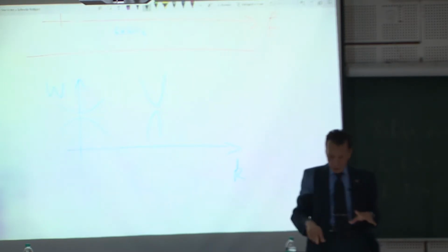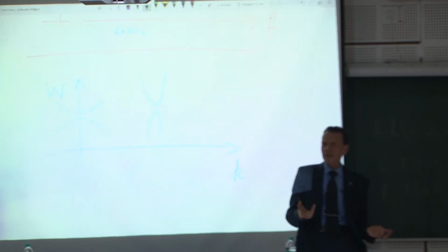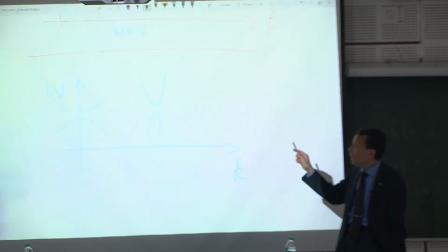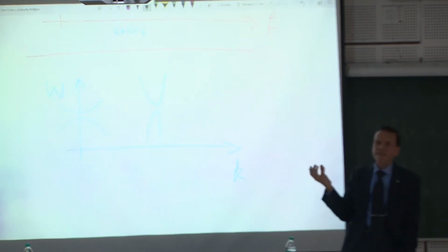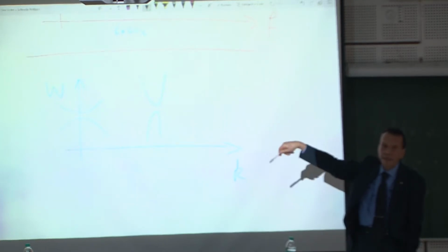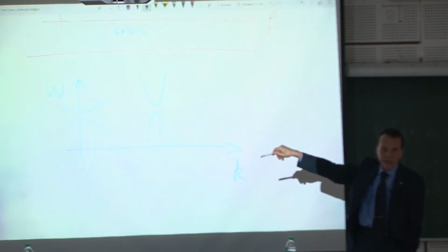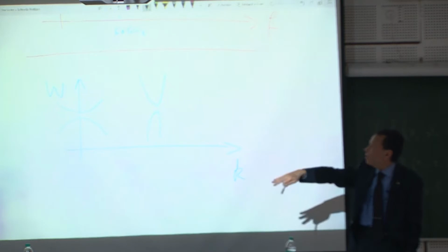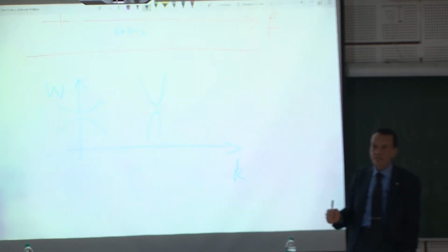Okay? So maybe if you remember the Gunn element. The Gunn element you had, but not for this purpose. In the Gunn element, you had also two areas like that. And most of the carriers were collected in the first cluster here, and at a certain applied voltage, they go to the other one. All of a sudden, so they become faster, and this is actually essential for the operation of the Gunn element. Okay, if you still remember what you had in semiconductor physics.